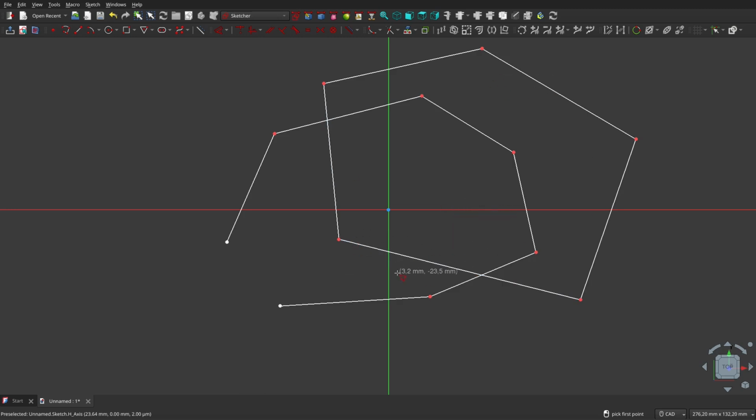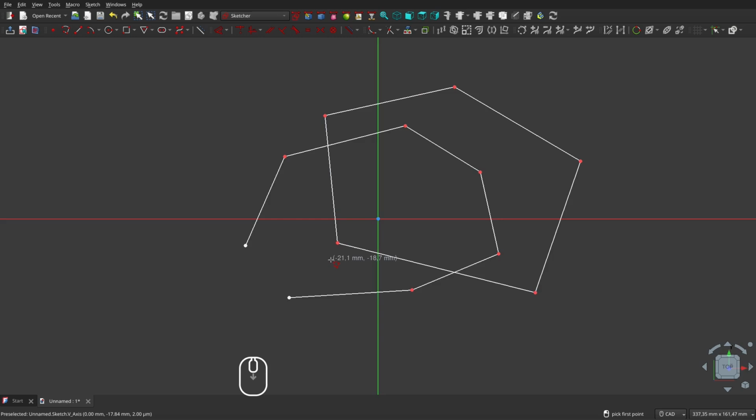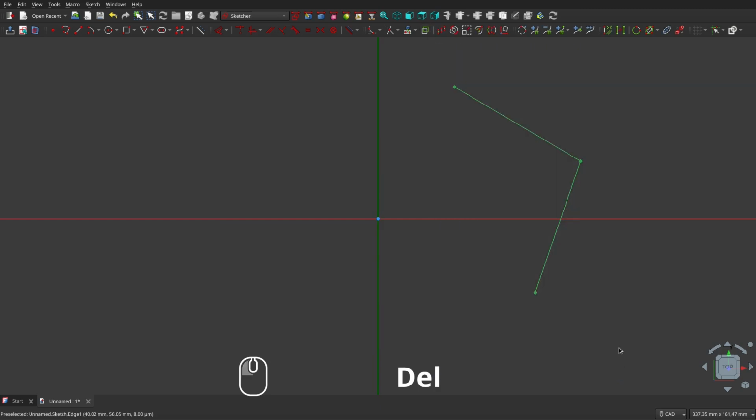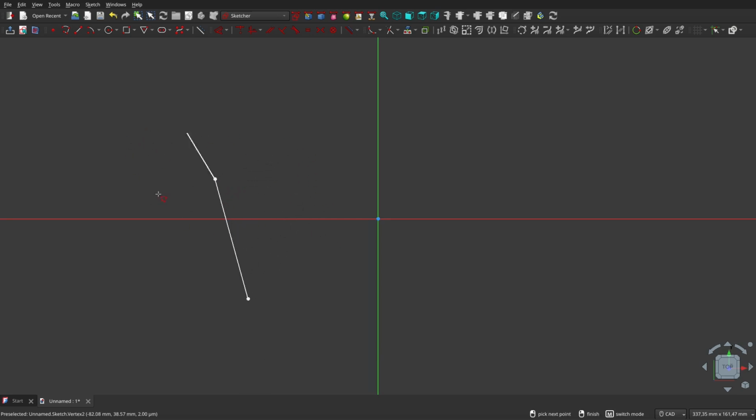That's not all you can do, though. Let's erase this. You can also create circular arcs and other constrained segments relative to the previous geometry. Let's start over here. Create the polyline. First point anywhere. Second point as well, no constraints yet. And then on the third point, we can start applying constraints.